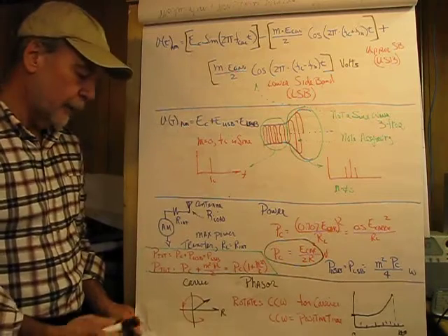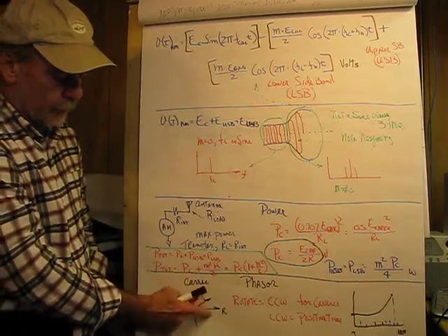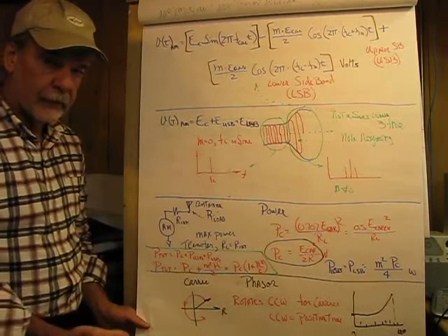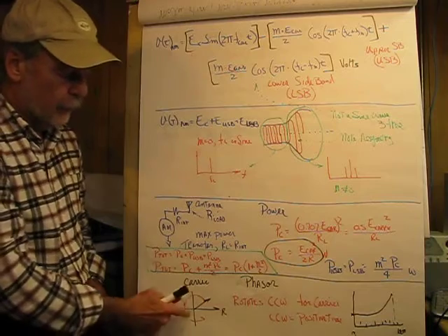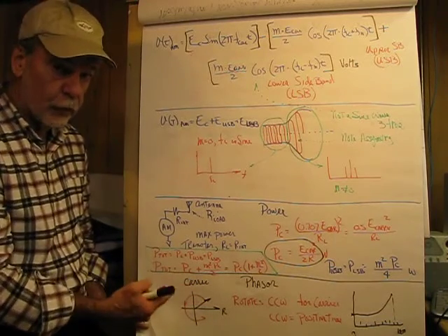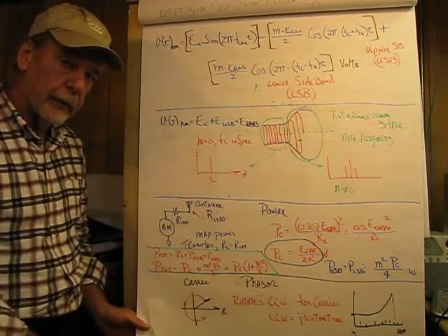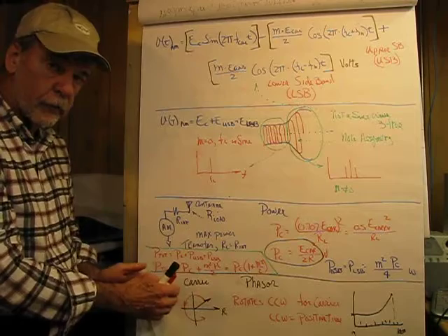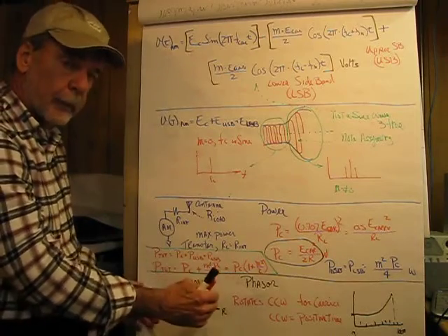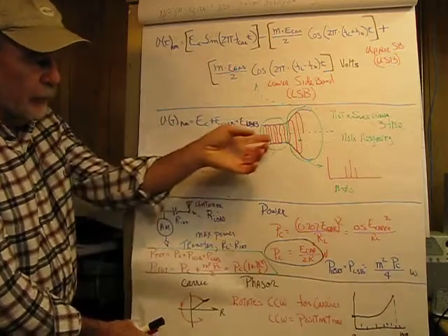Now, that may seem a little bit ridiculous. If we look at a carrier and have the phasor go counterclockwise, it's kind of meaningless. However, coming up, if we reference the sidebands to the carrier, it's perfectly okay to have a phasor turning in the clockwise direction. So basically what we did is we shifted from 0 hertz up to 1 megahertz, and then we'll analyze the phasors and see how they make this waveform.